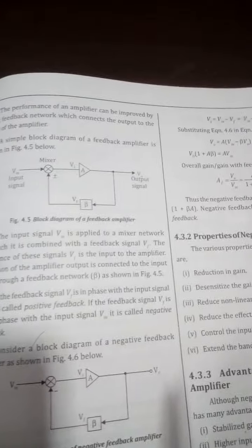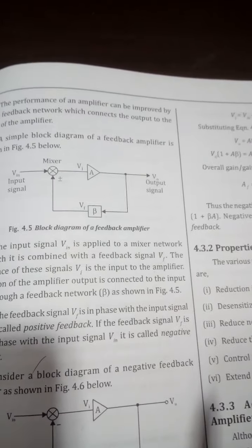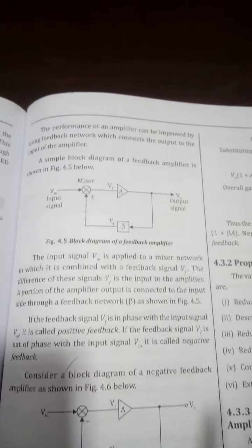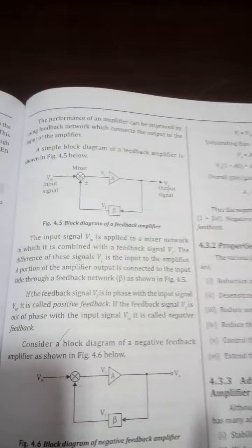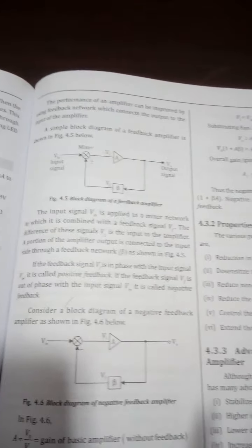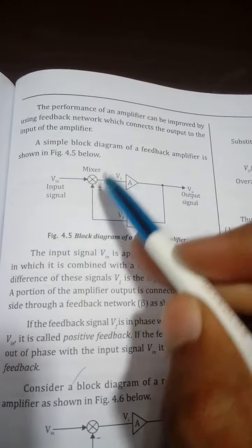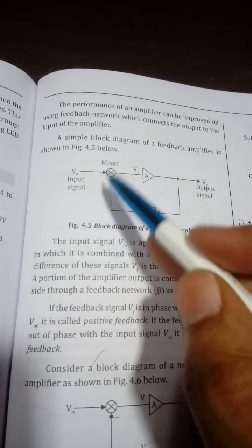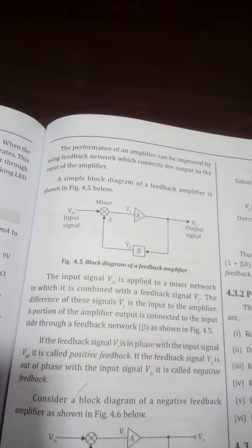And now we will see what is a feedback amplifier. A feedback amplifier is one which is used to amplify the input signal without changing any of its characteristics except the amplitude. It literally means that you are giving the output back to the input as a feedback, so that you can amplify, and also for the correction factor. This shows the diagram of a feedback amplifier. So this is the amplifier. The output from the amplifier, it has some gain, is fed back to the input through a mixer, and that goes back as the input to the amplifier.